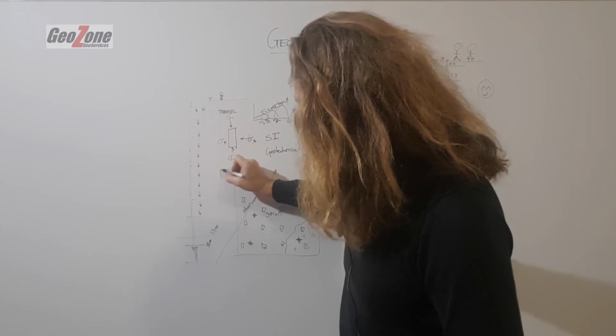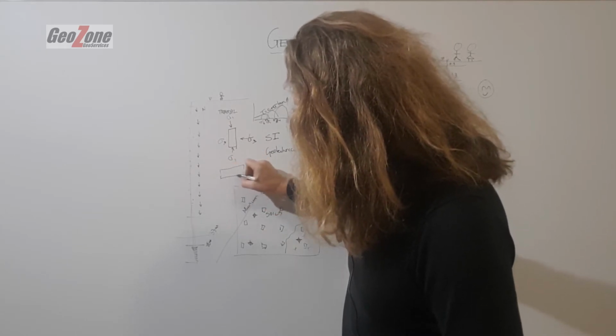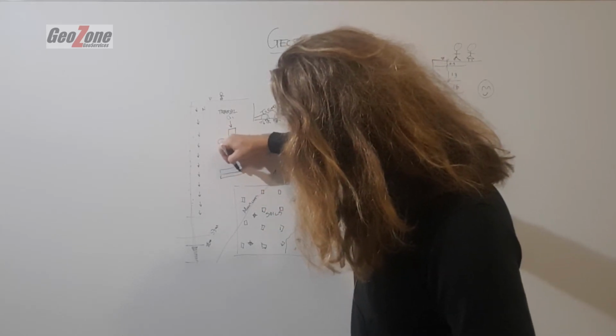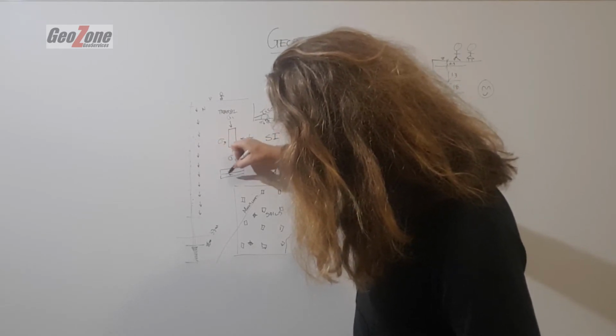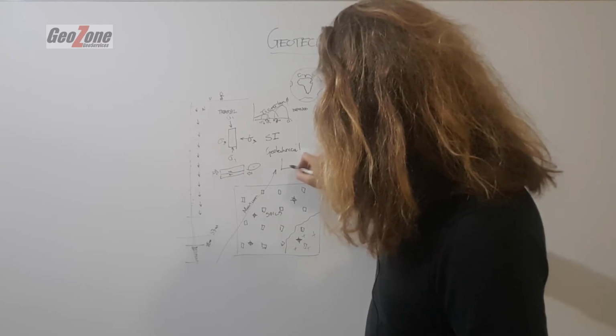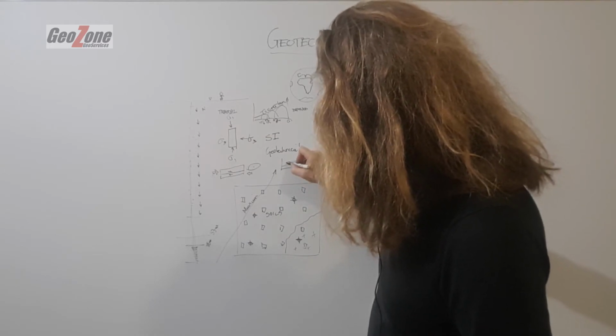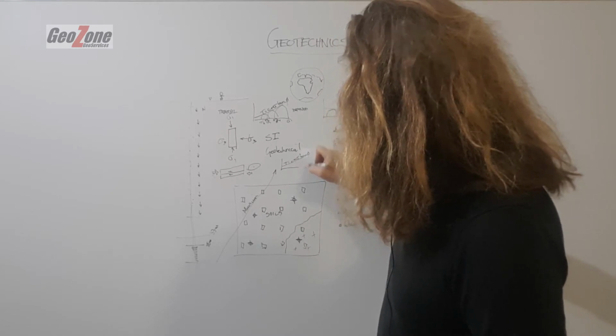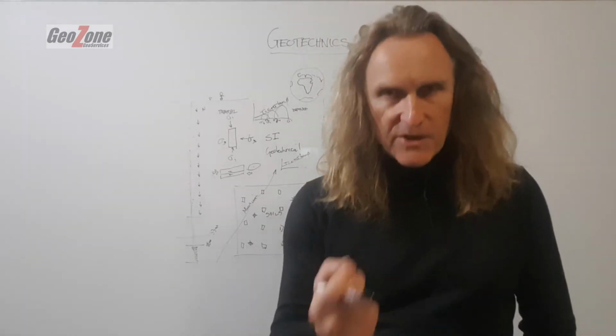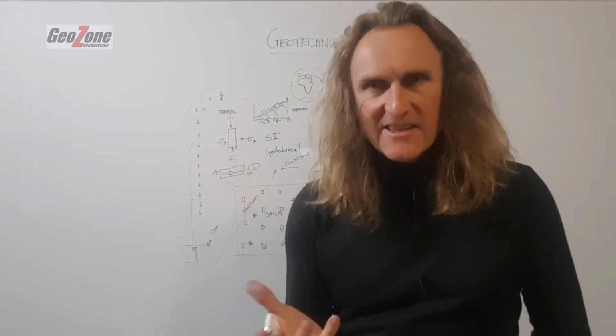The cheap version, not anywhere near as good, because unfortunately you're shearing a sample through a known line. But if you shear this way and that way, then you can also come up with your shear strength parameters: tau equals C plus sigma tan phi. A wonderful thing. But if we don't do the laboratory testing, we're guessing.